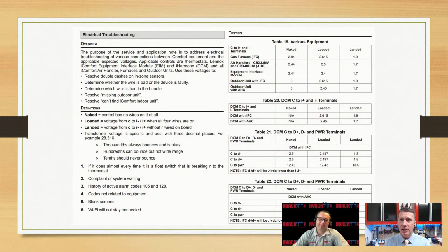You clean it to fresh copper. You put a new wire nut on it, or you don't even use a wire nut. Solder, because even a butt connector can corrode. If you're using any type of solderless connector, make sure that you fill that with silicone or dielectric grease when you're done, so you don't get moisture or any oxidation down the road.